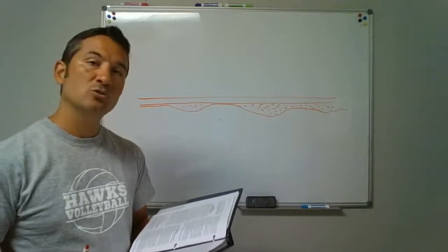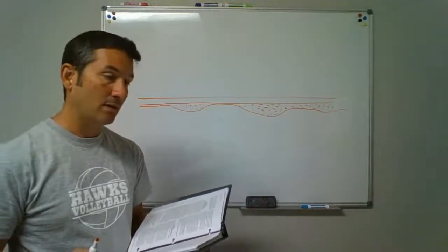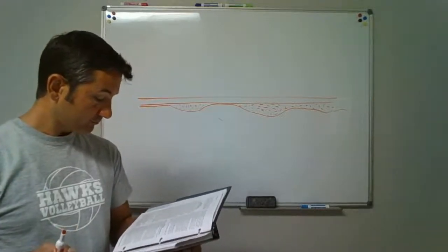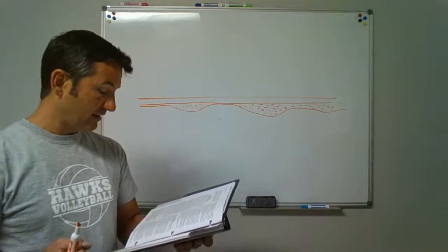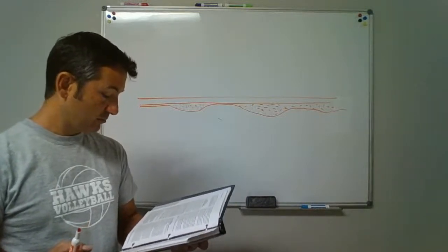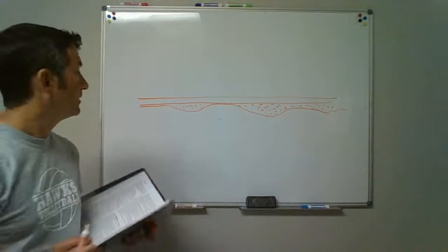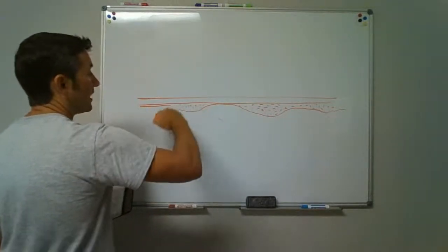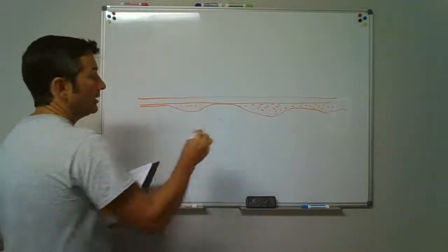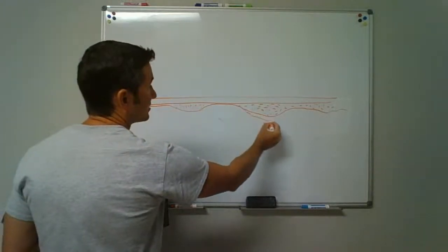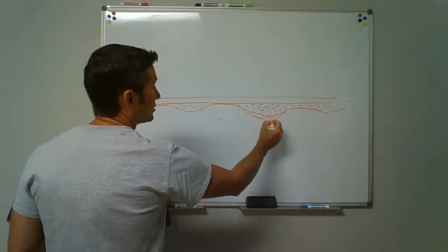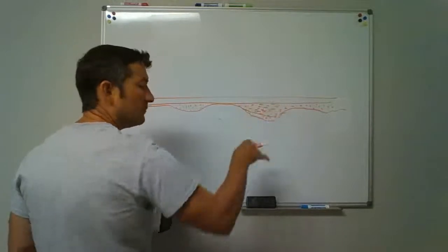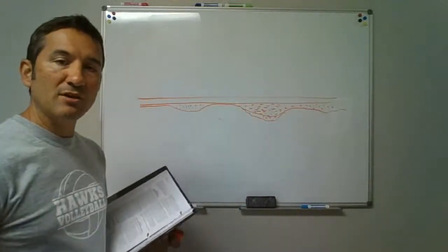It says now you've got to go sand or fine gravel, because you can't compact those like you can regular dirt. It says put them back in there in layers of 6 inches deep, and they shall be compacted after each placement. So as long as these aren't deeper than 6 inches, you can put sand or fine gravel, pack it down, and you're good. If it went deeper, you've got to put 6 inches maximum, pack it, and keep filling back up and packing it, getting that thing tamped really good.